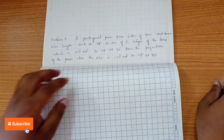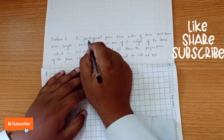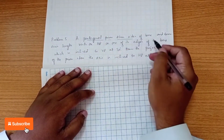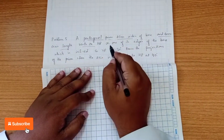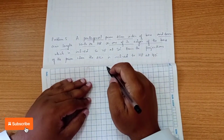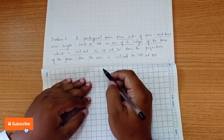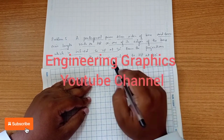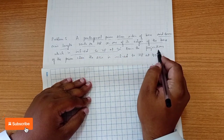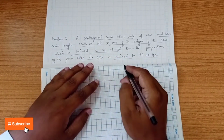Problem number 5 from the CAD solution book. What is given in the question is a pentagonal prism, dimension 25 and axis length 60. It rests on HP on one of its edges of the base. So we have to get the edge on the right hand side, which is inclined to VP at 30 degree. So here it is base edge inclination to the VP at 30 degree. Draw the projections of the prism when the axis is inclined to HP at 40 degree.